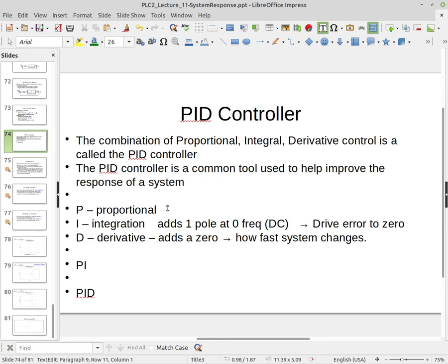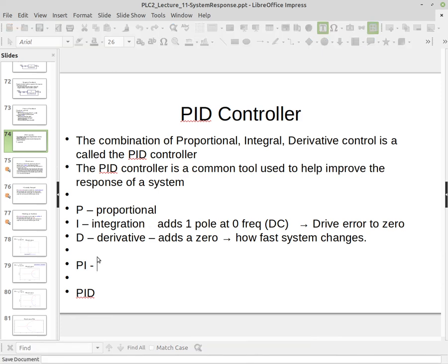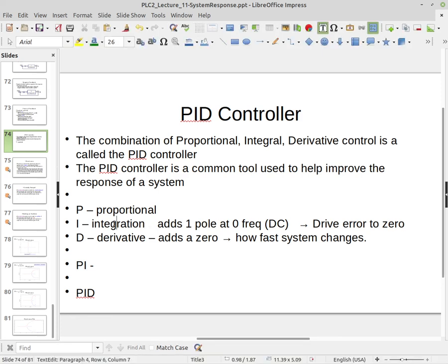So remember that the key component of the integrator piece is that if you have enough energy in your system, you can drive your steady state error to 0. But when you do these controls, you have to be careful that you're not trying to push them harder than they can go, and you also need to be careful because you can push them into instability. So even though the system is stable, if you add a controller, you could drive it unstable.